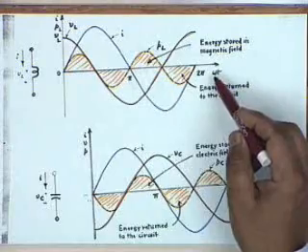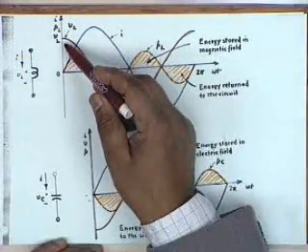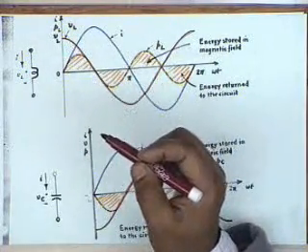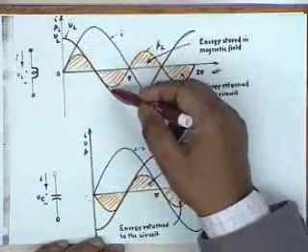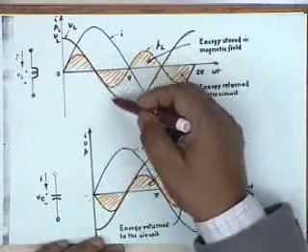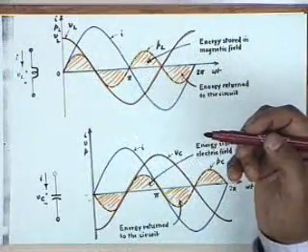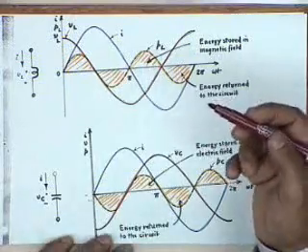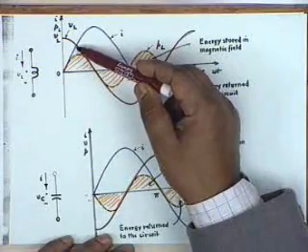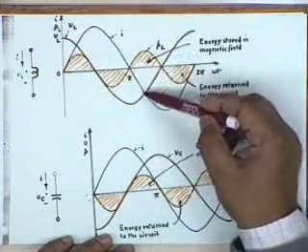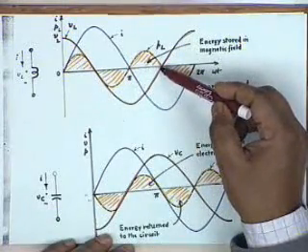Alright, when omega t is less than the maximum of this by 90, the voltage reaches its maximum, because the voltage is 90 degrees ahead of the current, and therefore this curve, what color is it? Red. The red colored curve is that of the voltage across the inductance, and the instantaneous power is the product of the two, and therefore whenever the current and voltage are both positive or both negative, you see this portion, current and voltage are both negative, the power, instantaneous power is positive.